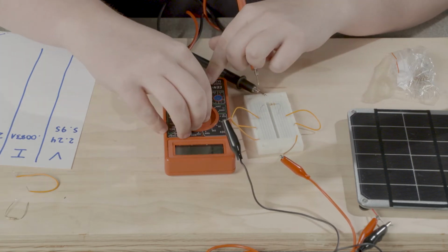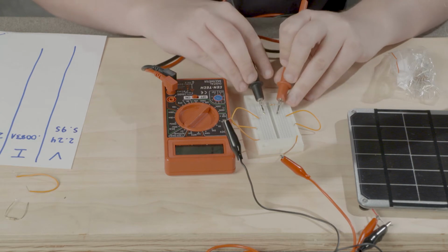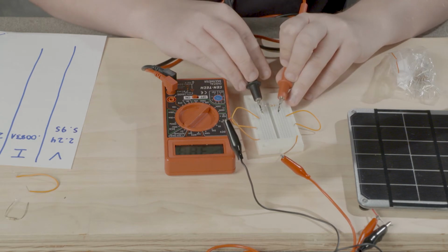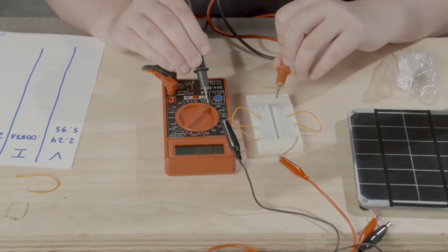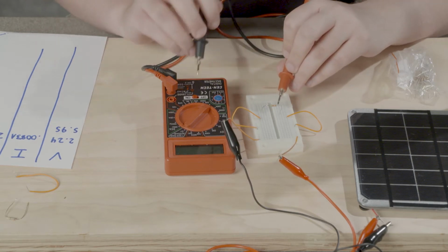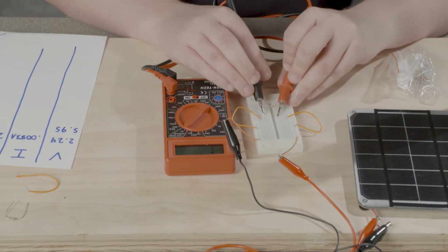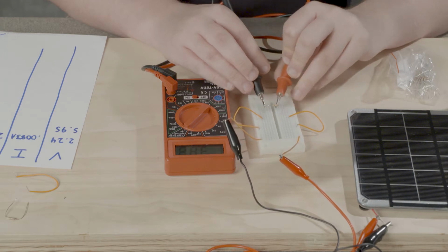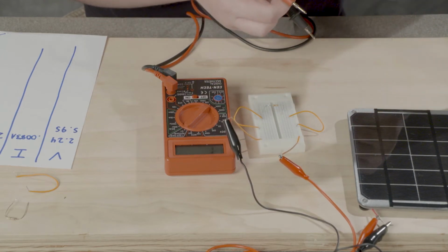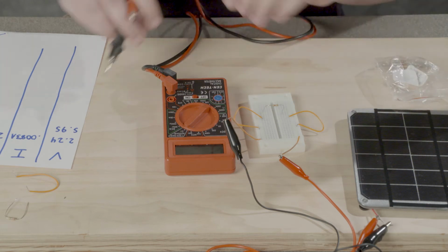Oh, I guess I was right there. Okay, so because we're on the range of 20 kiloohms here, that's the highest it will be. So we're actually in kiloohms. So this reading says we have 3.88. Well, that means we have a 3.88 kiloohm resistor, which is probably what we have in there.